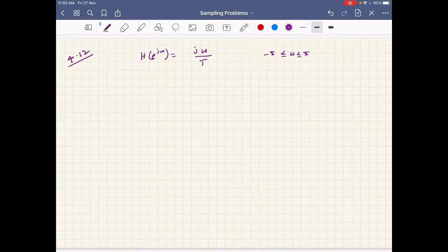Think of. Okay. So you have xc of t, which is given as cos 6 pi t. This is the first question. For the second question, it is cos 14 pi t. I will tell that later. And this xc of t, first analog to digital conversion is done. That means there is a sampler and so on. Sampling with capital T, and this capital T is equal to 1 by 10.